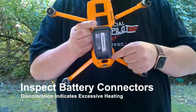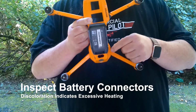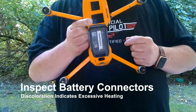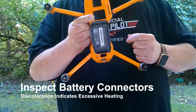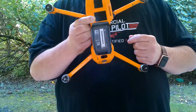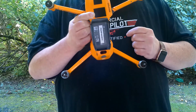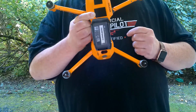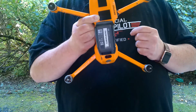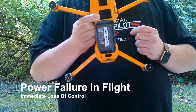We need to inspect the electrical connectors to make sure that they're all there, that there are none broken, and that none of them are severely discolored. That would prevent the battery from making a complete connection. You don't want to suffer any type of power failure once you're in the air.